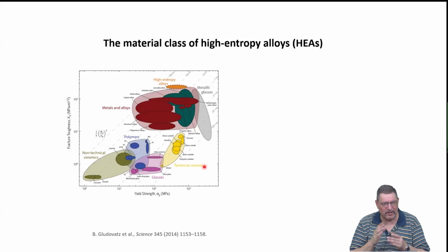When you see really a lot of twinning happening in the material, that is typically in a range of high strain rates. So it means shock absorption, high strain rates. Twinning can be easily initiated because all the other processes are not as quick as a twinning transformation. Transformation-induced plasticity means there are martensite-austenite transformations occurring, giving plasticity.